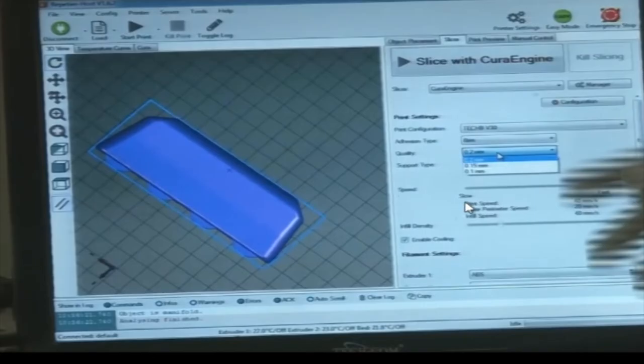And also, as I said, quality and speed are countering each other. If the quality is higher, the speed would be lower, because with 0.1 mm versus 0.2 mm, obviously the speed would be 50% of 0.2 if I use 0.1, okay, because 50% of the layer size is being deposited at each layer, at each slice.